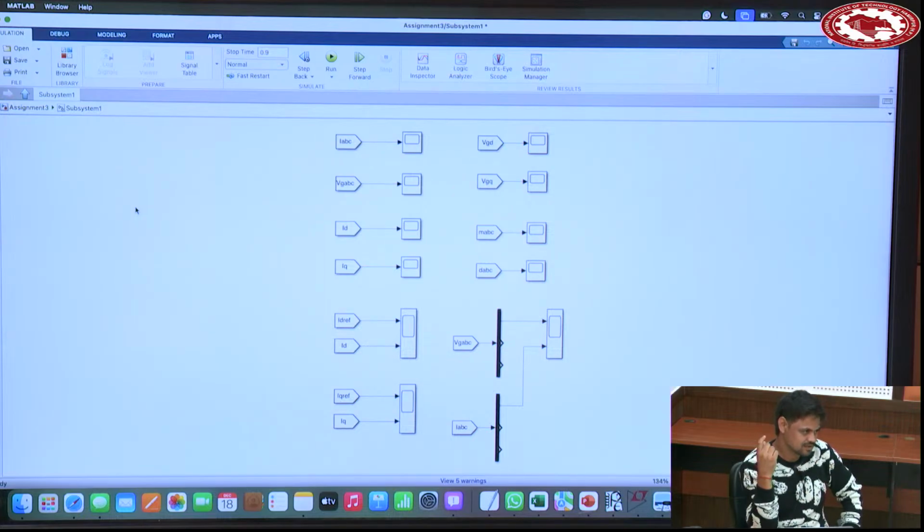We have divided by a factor of VDC by 2. Yes. Ideally, we have to divide VDC by 2. So the DC link should be chosen appropriately so that in rated condition your converter operates at 0.8 or 0.85. If you have taken the DC link too small, you have not given any margin. At rated condition the converter is designed for 10 kilowatt power. So when it operates at 10 kilowatt, it will have a modulation index of 1.